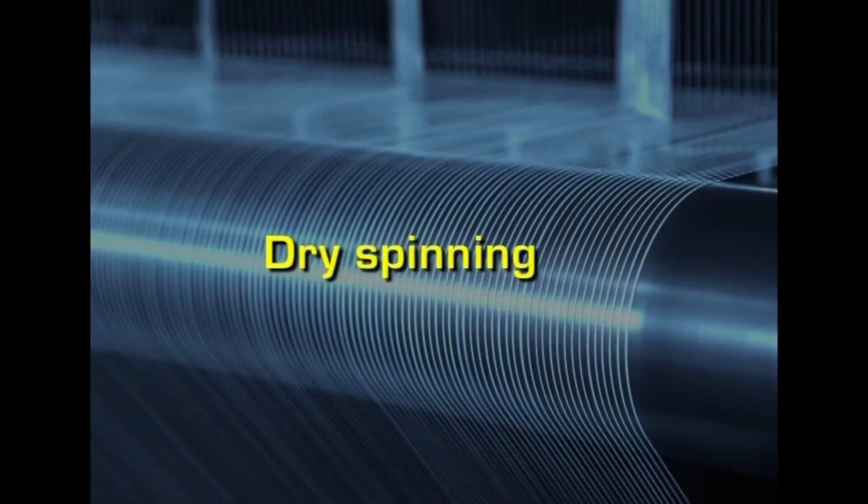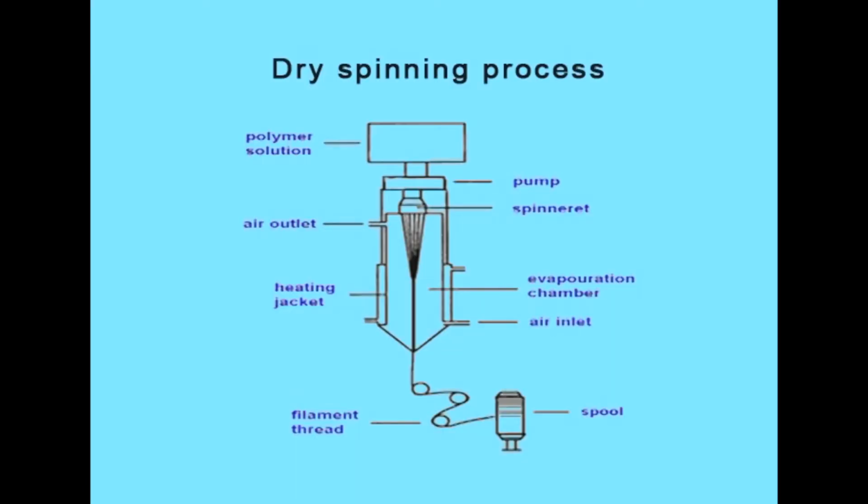The second method of chemical spinning is dry spinning. So, when the polymer is not of the melting or thermoplastic type, we have to see whether there is any volatile solvent that is applicable to that particular polymer. If so, then we can go for dry spinning. This is also a simple method wherein the polymer is dissolved in a solvent, extruded through the holes of the spinneret, and then it gets solidified through evaporation of the solvent.